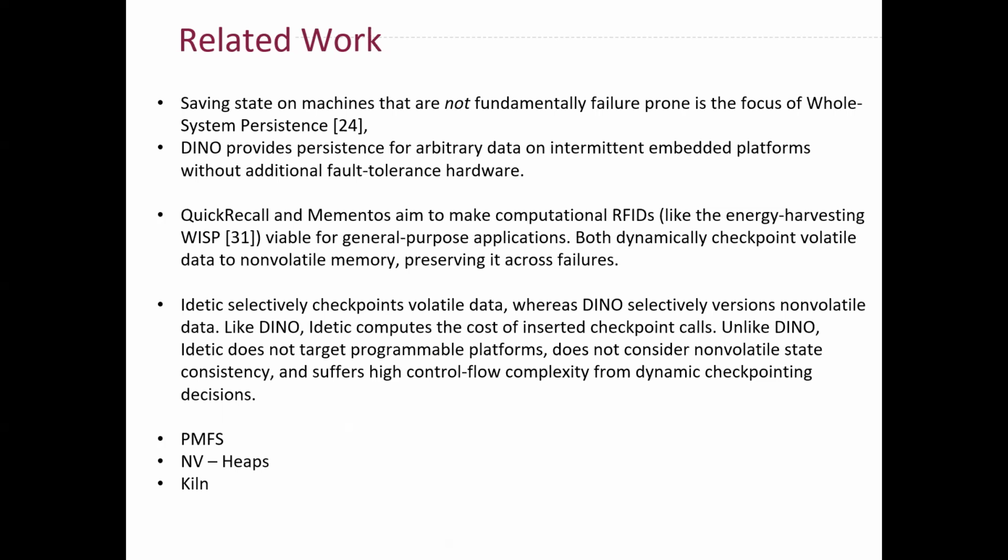Another related work is NV-Heaps, which considers the safety of memory-mapped non-volatile heaps, focusing on pointer integrity, and provides a programming construct for non-volatile transactions. DINO's task atomicity could be implemented along with NV-Heaps' generational locks, but DINO's operation is fundamentally different from heap management, since embedded systems generally avoid dynamic allocation.